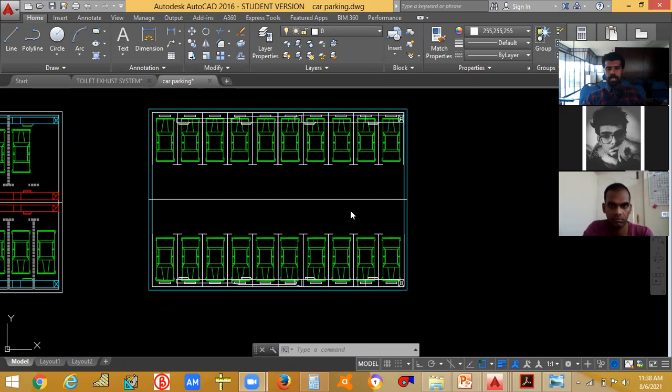So first thing is that we have to study the project. We need to see what the area is, and according to the area and the site conditions, we'll be deciding whether we need to give a ducted or a non-ducted system. That's right. If we choose to give a ducted system, the first thing we need to do is find the CFM of it.